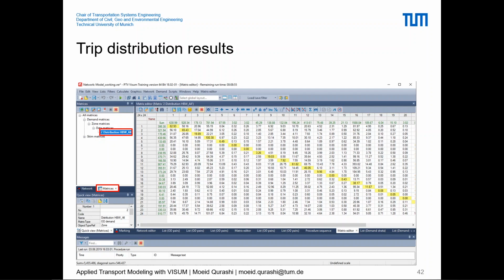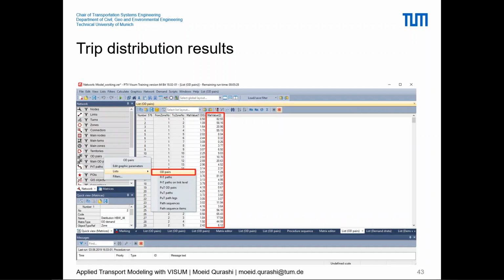And what we try to do is create an optimized size of all the zones, so that we minimize the trips that are within one zone. We already had a discussion of this before as well. So this can be done either if we have homogeneous land use within a zone, and also we try to reduce the sizes of the zones. So that's it.